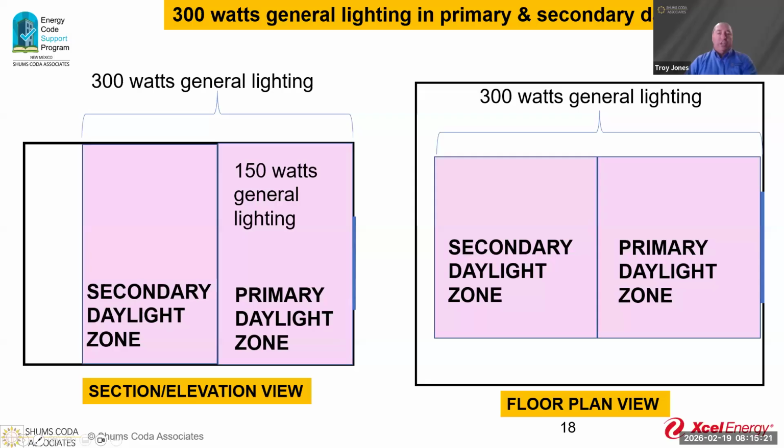So Paul has a question here. He says if there are windows with a high solar heat gain factor for cooling loads, do the controls take care of the light level? Yes, that's exactly what those responsive controls do, Paul. Again, we have sensors in the rooms that are calibrated for the amount of light that's coming in from the exterior, and that dims the lights inside that area to maintain the appropriate lighting. So that way we're not using as much energy. Great question, Paul.